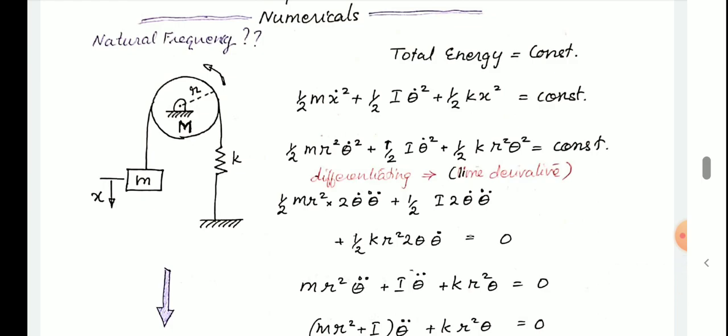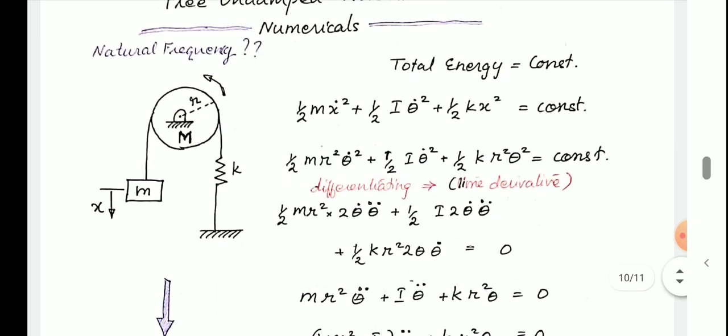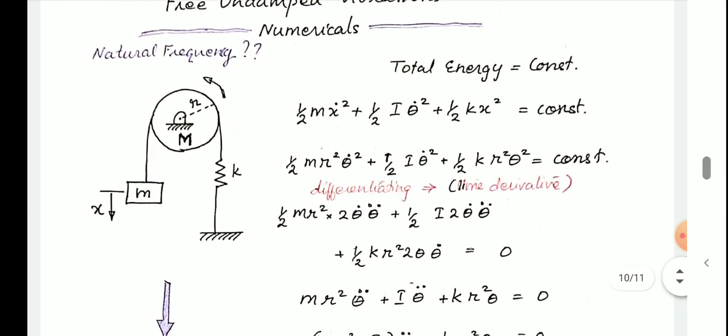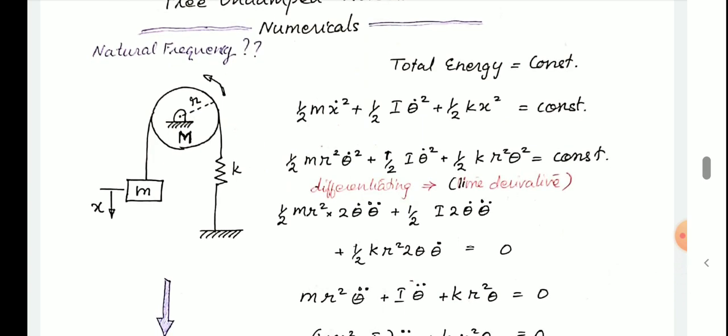instead of the linear or translational displacement x, you should be using the term theta there, the angular displacement. Remember the rotational body and the equations which we have written for that rotating disc hanging from a shaft. So theta is the angular displacement, theta dot will be the angular velocity, and in place of mass m, the rotational equivalent we take is I, which is moment of inertia.